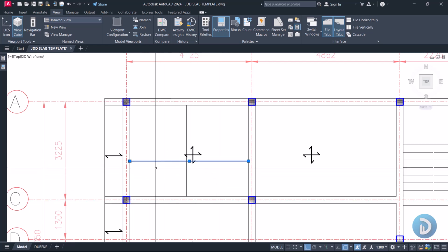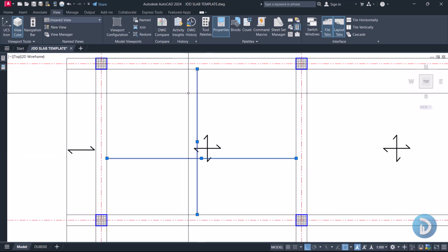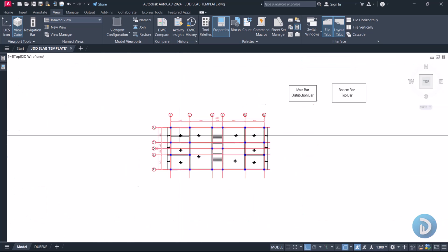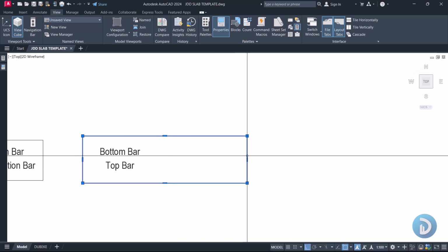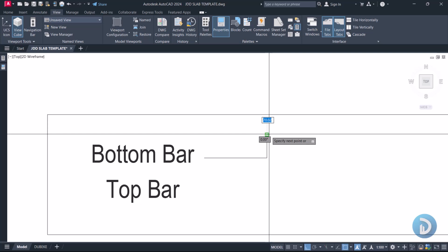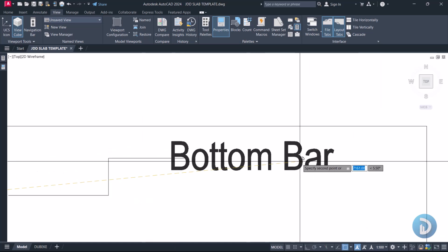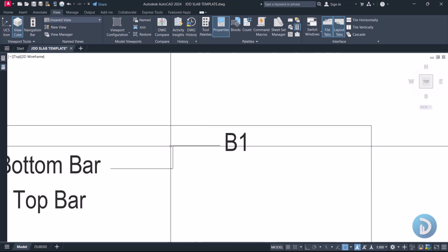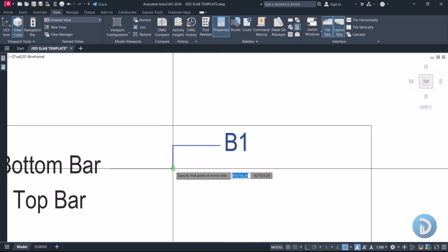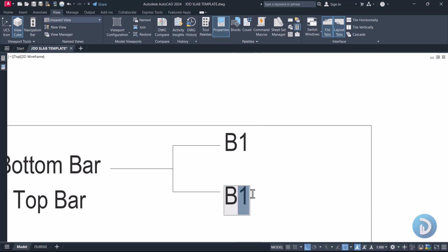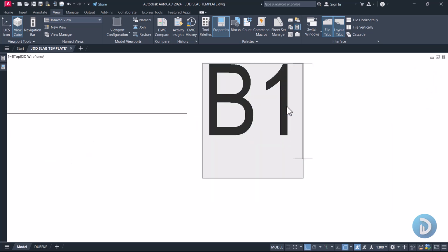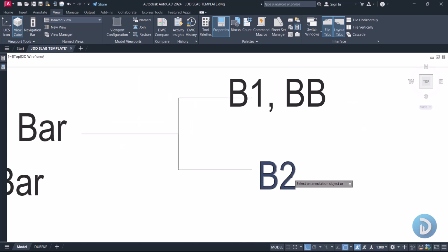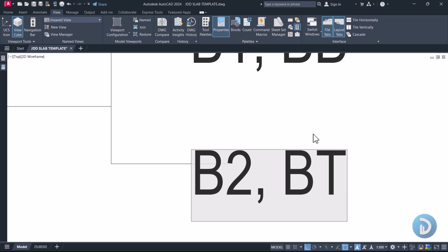So this one will serve as the reinforcement running directly on this other reinforcement that is running at the shorter span. So they are both bottom bars, but one will be placed on top of the other. That's to say, at the bottom zone we should have indications of another layer of reinforcement, which will be our bottom one reinforcement. Then we should also have another layer of reinforcement, which should be our bottom two. We can also refer to the bottom one, which is the one running at the shorter span, as our bottom reinforcement. Then this can be referred to as our bottom top reinforcement.